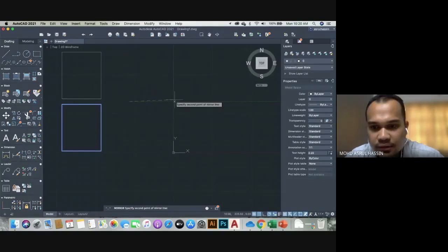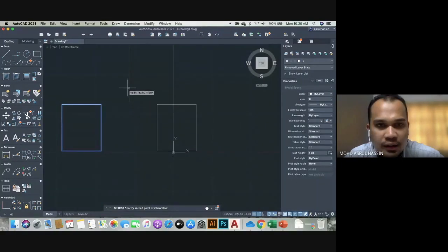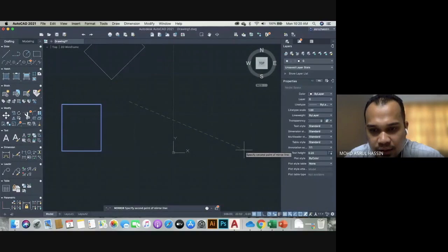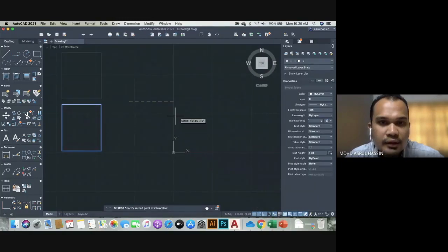So if you want to make sure this line only moves every 90 degrees, you see at the bottom the auto mode. Okay, you just click the auto mode. Okay, it means this line will go every 90 degrees.